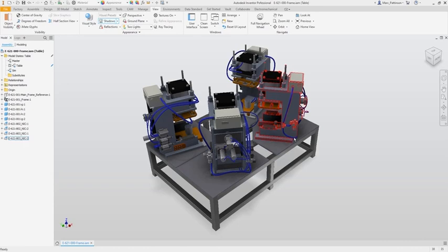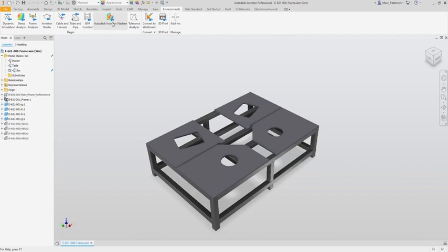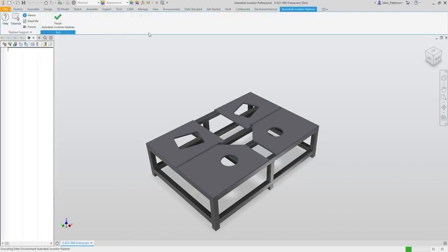In this short presentation today, we will only be scratching the surface of Inventor Nastran's capabilities. Let's take a look at Inventor Nastran embedded directly inside of Inventor. But first off, let's select the model state which we require for our simulation, turning off all those unnecessary components and being able to utilize the capabilities of model states directly inside Inventor and Inventor Nastran.